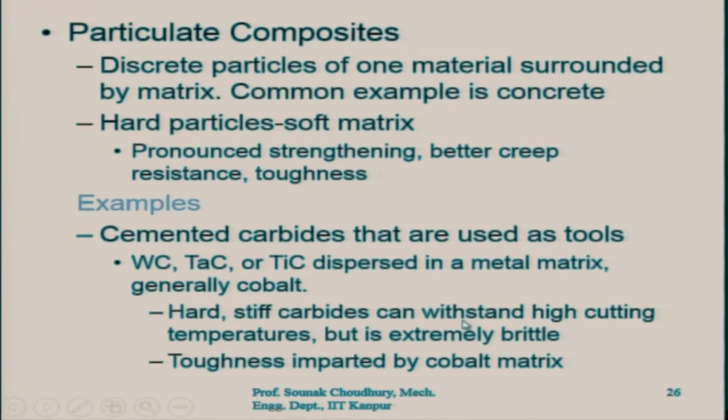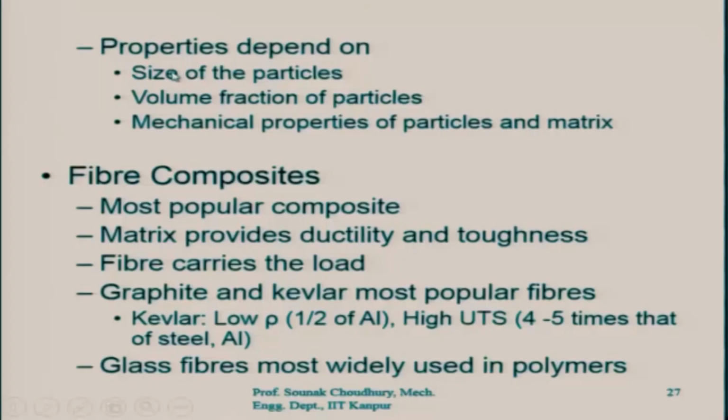Hard, stiff carbides can withstand high cutting temperatures, which is very important, but they are extremely brittle. Toughness is imparted by the cobalt matrix, so the cobalt matrix improves the shock absorption property to an extent. Properties also depend on the size of the particles, the volume fraction of particles, that is, what fraction of the volume is those particles, and the mechanical properties of both the particles and the matrix.